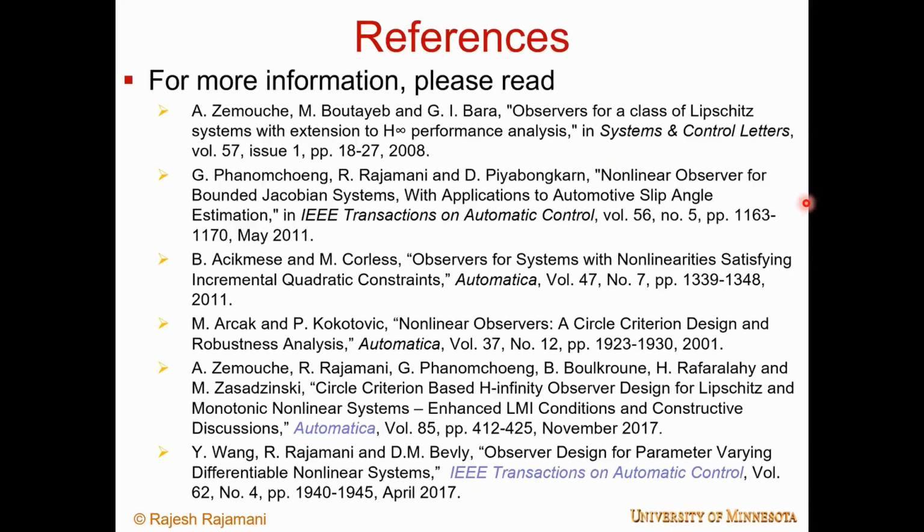So we don't need to solve these LMIs in real time, because what you need to do is find a solution to the LMI offline, and typically in many of these applications, the L is a constant observer gain matrix. And so once you find L, you can use that L in your observer, and you don't need to keep solving the LMI in real time. You just solve it once, and that would be adequate.